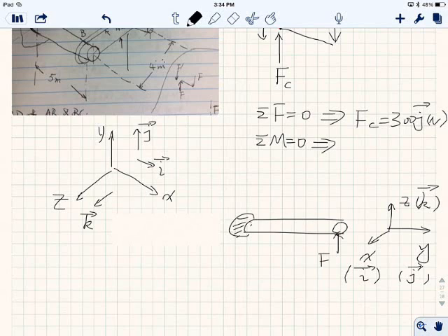So if I have a force pushing up, let me not say it's fixed. Just say this beam is simply supported at the end, so it can rotate, right? So if this force is going upwards, this force will cause a moment for this beam to rotate. So how do I determine the direction of the moment? You use your four fingers to align with the direction of the force, and then it's going that way, right? So the thumb, of course, is moving outside of the paper. So it is the same direction as your X. So this M will be in the direction of I.